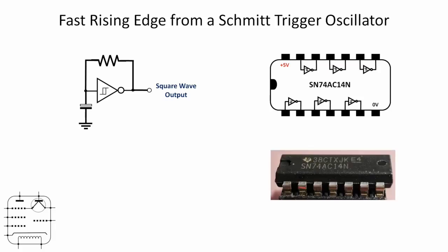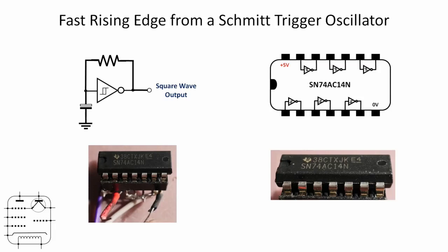So there is the little beastie, and I've tried to make it as efficient as possible, so I've built the entire circuit on the underside of a DIL socket, and the little red and black connections you can see there are where I'm going to attach the scope probes, so hopefully we'll get a minimum amount of interference. Okay, let's now go to the bench and have a look at how we might measure rise time on two scopes using the signal generator.